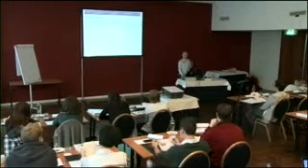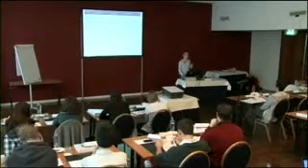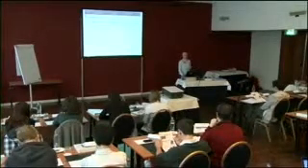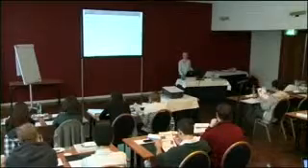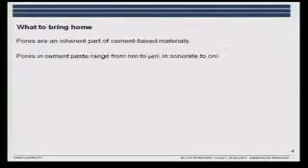So what to bring home? First of all, pores are an inherent part of the cement-based materials. We have them, we have to deal with them. Pores in cement paste range from nanometers to micrometers, and if you're talking about concrete, which we normally are, it will be to centimeter range.